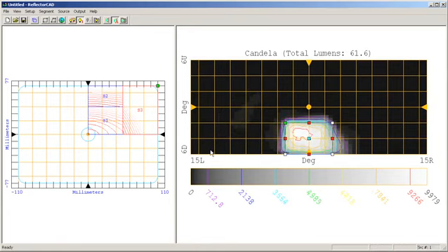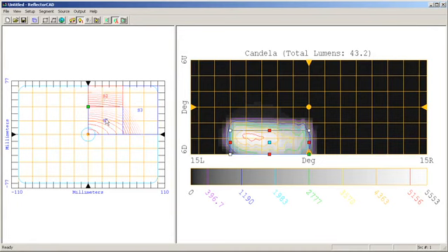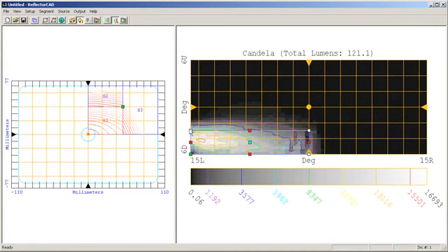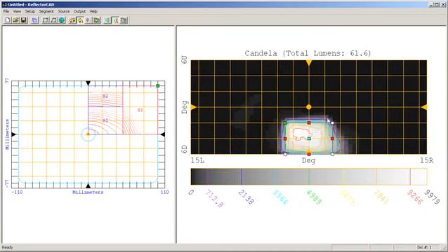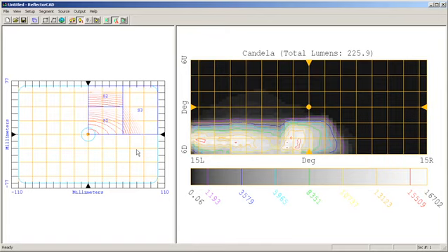You will note in the design that I'm doing, I'm actually tilting or adjusting the luminous intensity patterns from the inner segments to correspond to the luminous intensity pattern on the outer portion of the beam. And the segments which are furthest away from the lamp actually correspond to the luminous intensity patterns at the center of the beam itself. This is a standard practice in designing segment and reflector systems. What we can see now is the sum total of the distribution of those three segments.